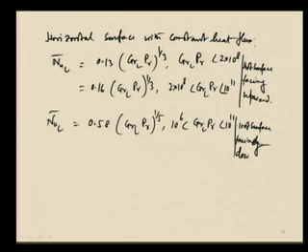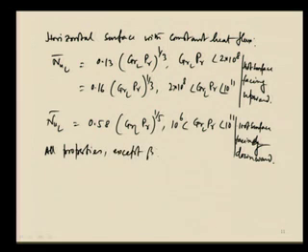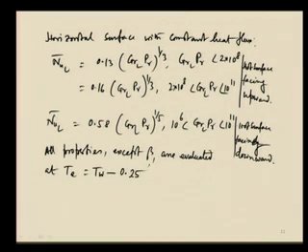Fine. And then all properties in this particular case, except beta, are evaluated at Te, and that is equal to Tw minus 0.25 into Tw minus T infinity. T infinity is the free stream temperature or the stagnant film temperature. Okay. That is what is being done.